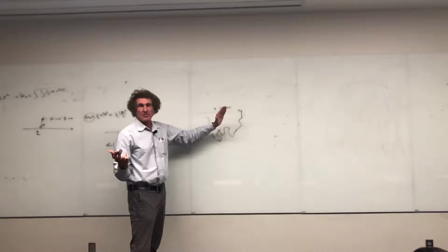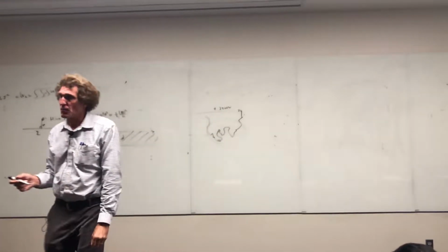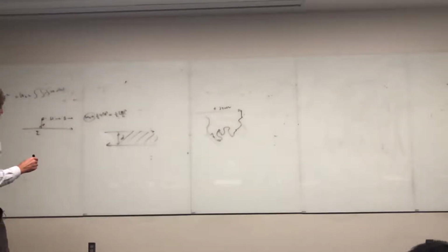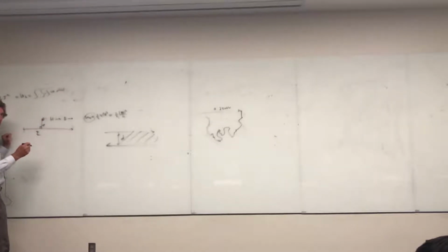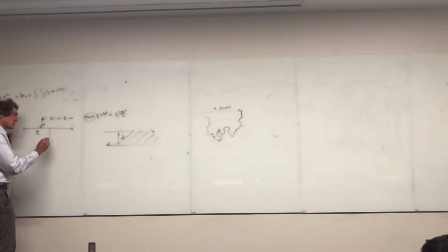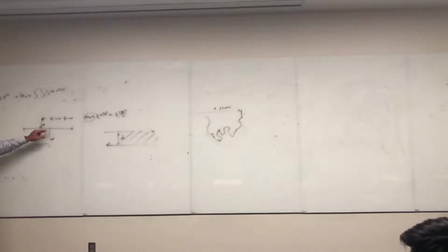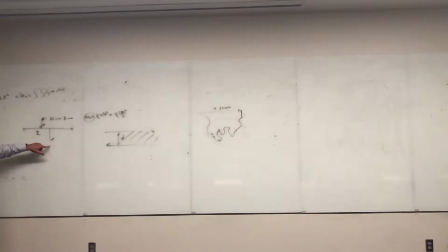So what they've developed is something called the partial inductance formula. And now it's only for external inductance. We know generally if you have a wire of a given length, if it's straight, all right, and I come out a distance rho from it, if I'm very close, I know what the magnetic field is here, right? I can get it. I can assume it's infinite. The further I go away, the more it looks like a short dipole in a sense, and I can get the magnetic field for that.